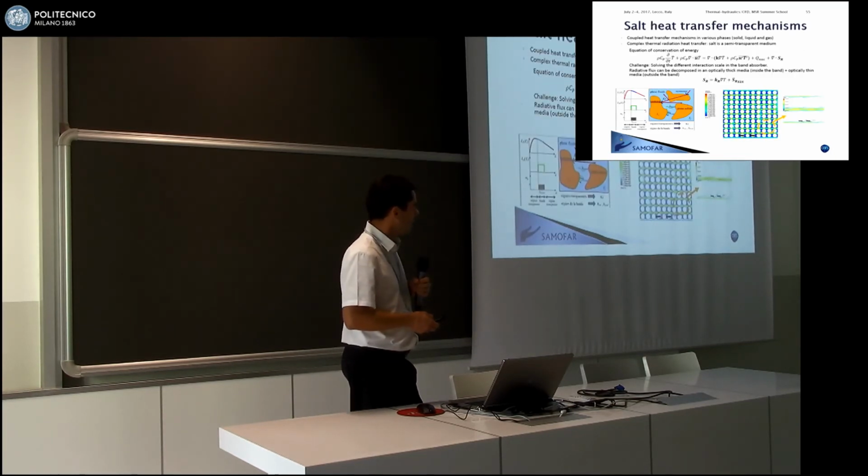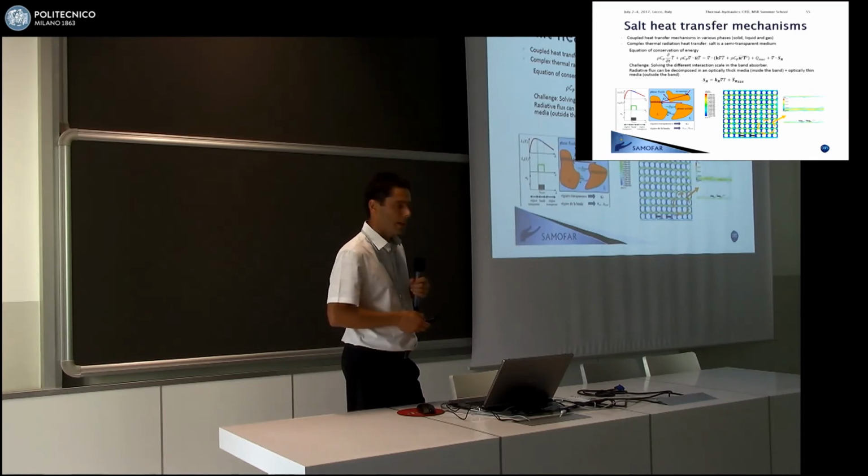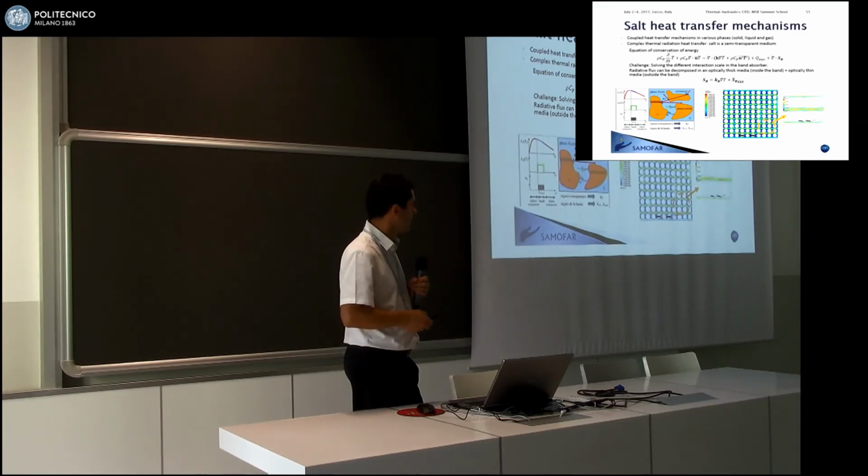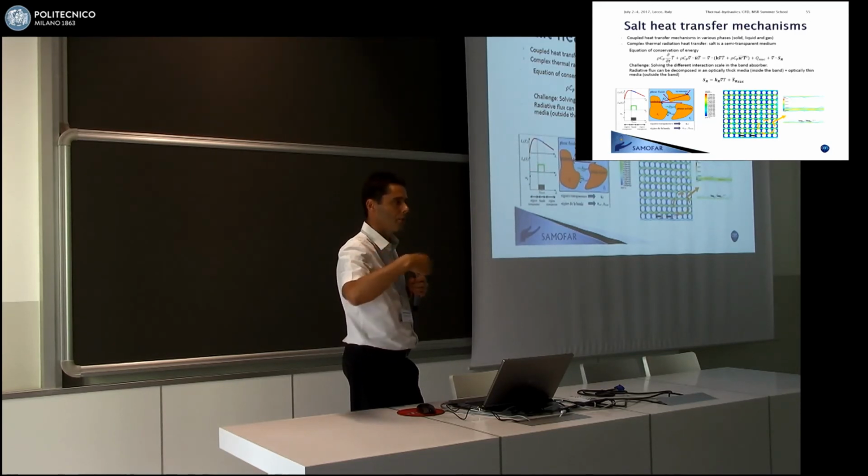Regarding heat transfer, in the salt, things are a little bit more complicated than in water because you have radiative heat transfer. And the salt can be considered as a semi-transparent medium. So that means that if, let's say here you have three particles, okay? The particle may be exchanging radiative heat outside a band. A band is a region where the fluid will absorb all the energy.